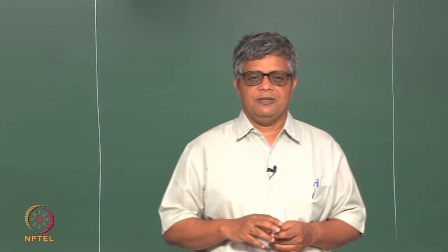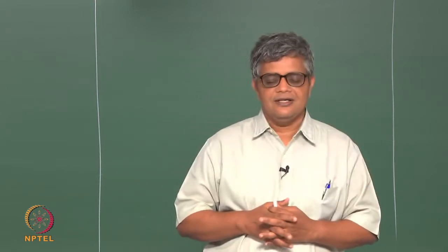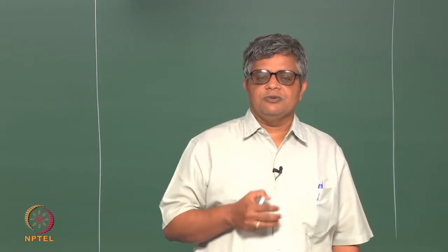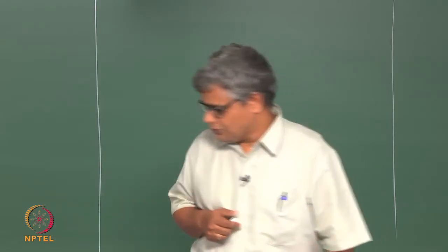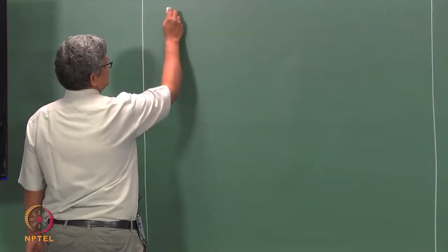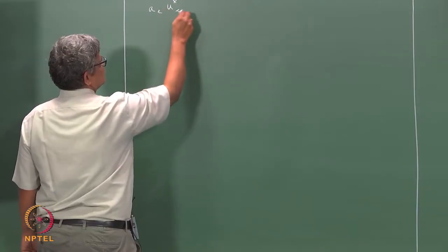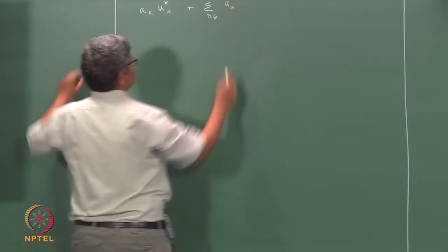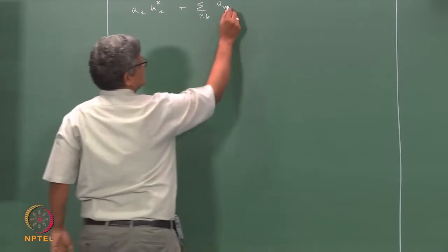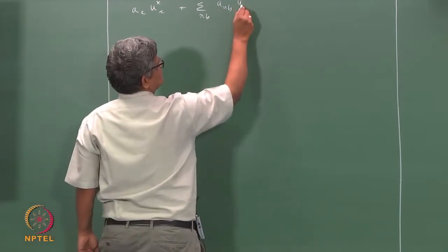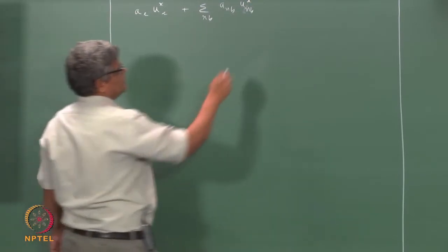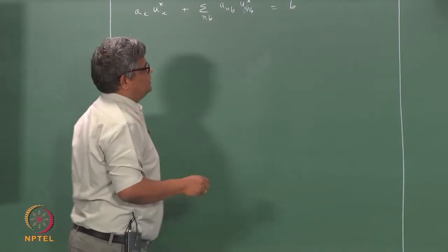and we converted that at a particular point at the face of the control volume of a point centered around the point where pressure is evaluated. We are going to draw the diagram, and we said that at this point we could approximate the x momentum equation and convert that into an equation for the discretized momentum equation, which we wrote as sum over the neighboring locations where u velocity is evaluated times their respective coefficients times the neighboring velocity component equal to a constant b, plus,